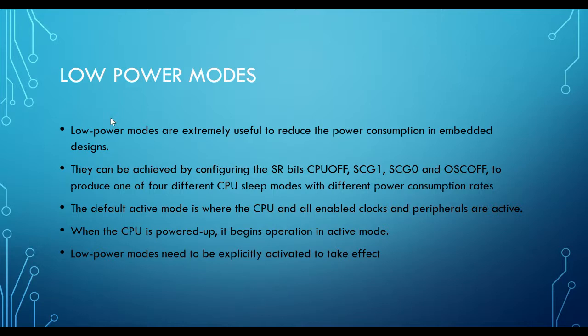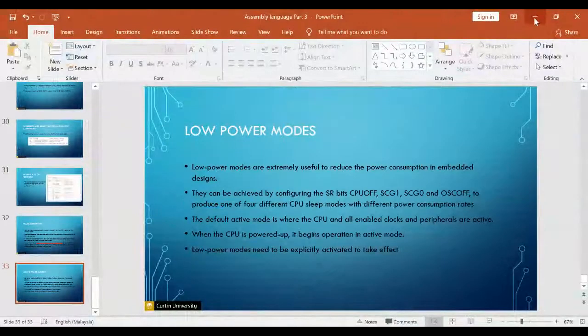This low power mode is not something that is specific to MSP products. You have Freescale, you have it. Microchip, you have it. All the main brands have this low power mode. It allows you to bring something to consume less power so that it doesn't draw too much. But you can turn it on again by using an interrupt. So if, let's say for example, a user presses the button, you can use the button to activate the CPU, etc. Okay, so I think we've come to the conclusion for this lecture.